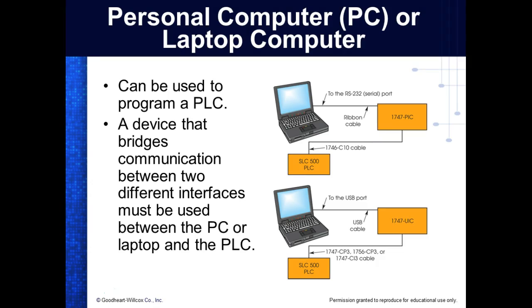You understand? And so normally we have to go between what interface the PLC uses, and we have to have some type of converter that goes between there. What's nice about Ethernet is you don't have to have a converter, because just about all your laptops now have it. If you buy one, by the way, laptops are getting thinner and thinner, right? So every time we get ones, we make sure we get one with an Ethernet jack on.